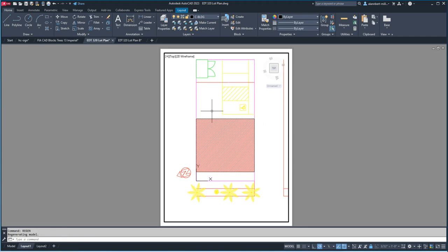So what it does is AutoCAD will now be sort of in charge of putting the linetype scale automatically, as long as your LT scale is set to 1 and your paper space LT scale is set to 1 also. So they're both on. So no matter what scale you use, AutoCAD will sort of adjust the linetype scaling based on this LT scale.